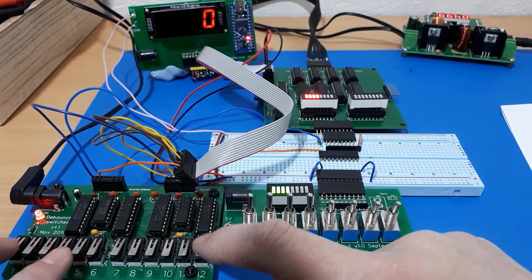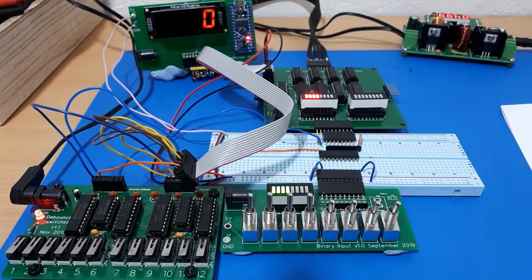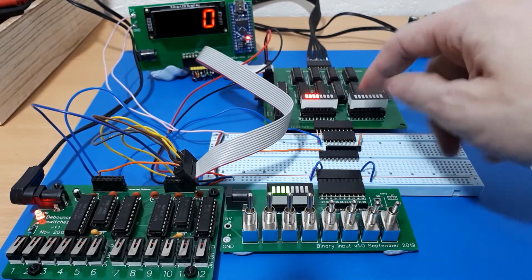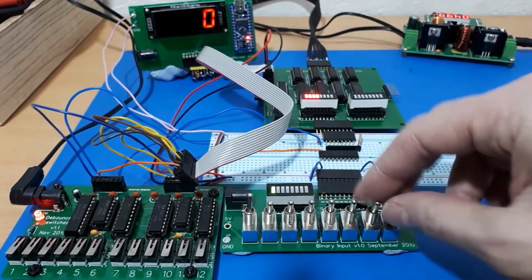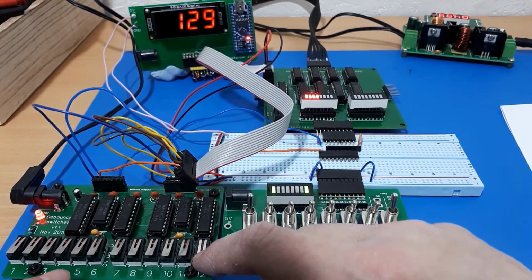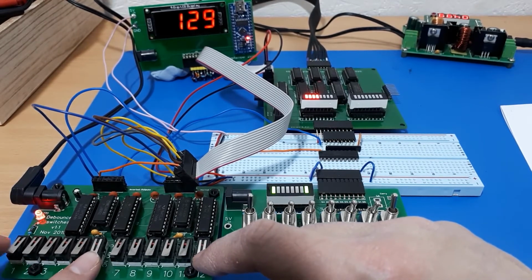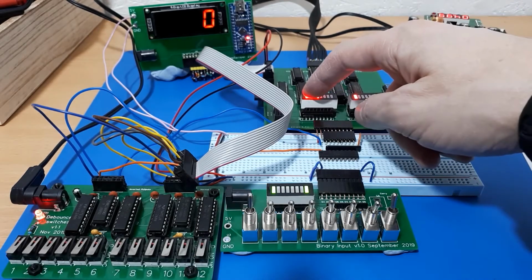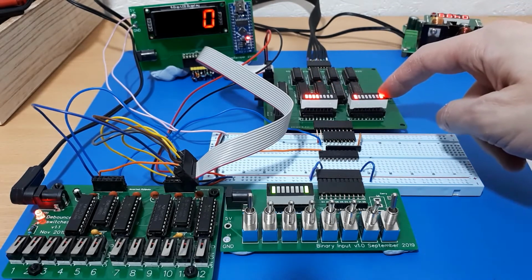There you go. Now the reason that I've done that is I don't want the program counter increasing at random intervals. I want to increase it exactly on a clock pulse. So in order to store for the program counter, you have to have a clock pulse going as well. So I've stored 240 in the high section there, and let's put 129, publish. Store for low is 6, so we hold down store and we do a clock pulse. So there you go, I've stored 240 in there, 129 in there.